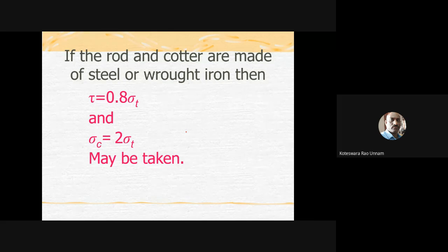In that you can clearly see that t is equal to 0.3 D, which is the same as d2 by 4 also. If you substitute that empirical relation, you will get t is equal to d2 by 4 only. So now use the second equation to solve for d2. Then crushing strength of spigot collar: use that relation to determine d3.